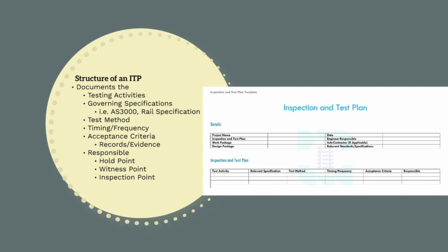The verifying record specifies what recorded evidence is required to prove that the inspection and testing has actually taken place and the outcome of the inspection and testing. So for our trenching example, we may attach a photo to our ITP of a tape measure in the trench to prove the depth of the excavation. Alternatively, this may not even be required, and we could just tick to say we had indeed inspected the works and verified the trench depth.